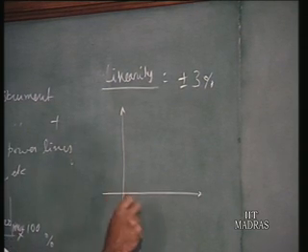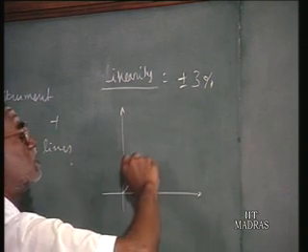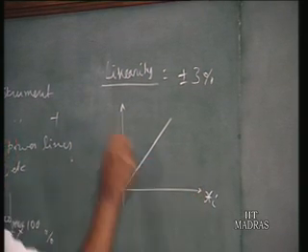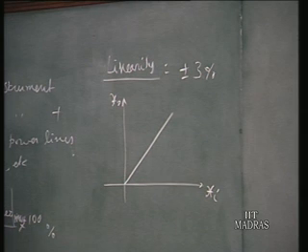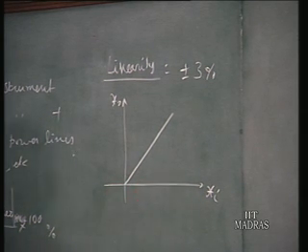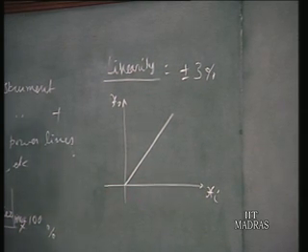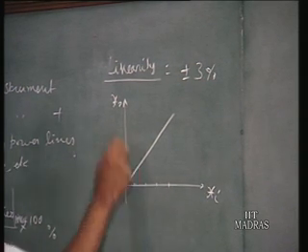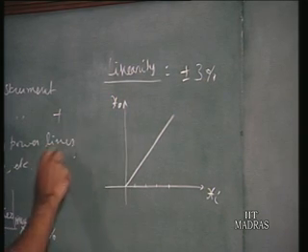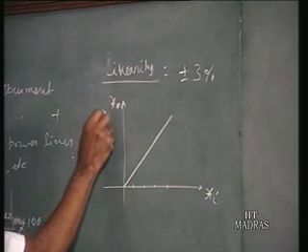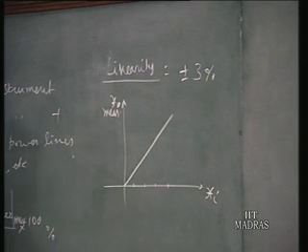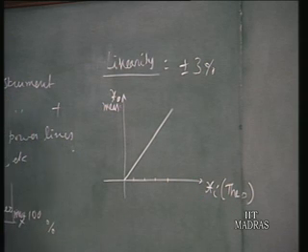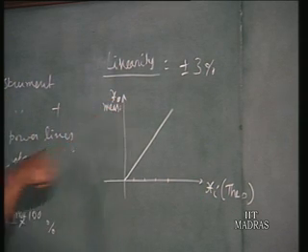So we conduct this, suppose the instrument is supposed to be linear. This is a characteristic of say xi and xo. And xi or pressure is varied from 0 to the maximum value. This is the way we are going to conduct the experiment. So at different inputs, we get readings. Actually xo is our indicated or measured reading. This is the measured value. And xi is our theoretical one, which is shown by our standard instrument, and xo is the measured value, shown by our instrument under study.